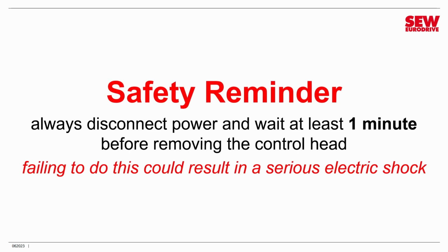But before we get started, just a little safety reminder, I'm going to say this again: always disconnect power and wait at least 1 full minute before removing the control head. Remember that control head can be charged up and you want to give the capacitors time to discharge, so waiting 1 minute is necessary. It prevents you from getting a serious electric shock.